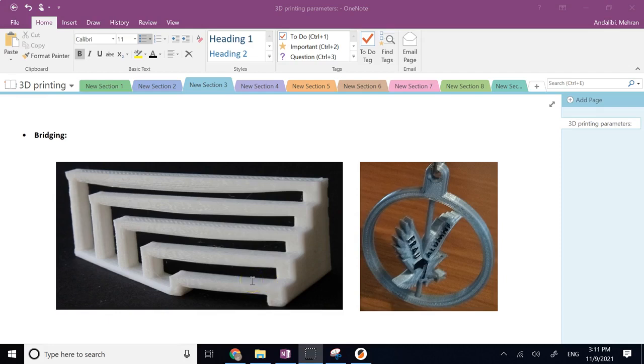And you might say, okay, what's the point if I can add support and avoid any sags like here? Why should I do that? And the answer is, for example, if you look at this part that I designed and printed, it is like an assembly. This is this eagle on this pin, and the pin is inside this kind of support or bearing in the main keychain or loop. And I have printed this whole thing in one piece. And when you print this and lay it flat, so I put the back side of it on the printer, then there are bearing areas, right?